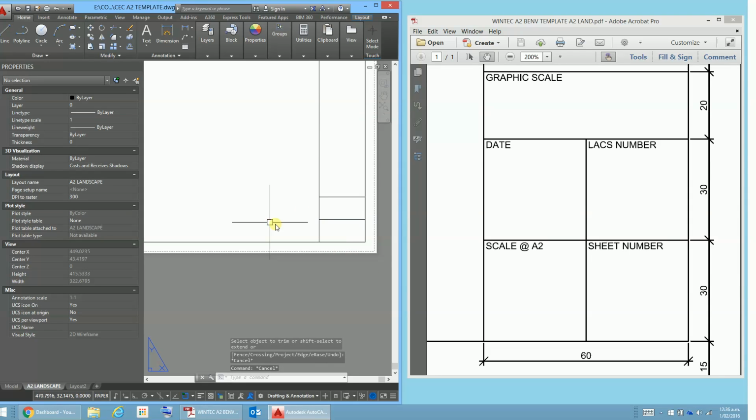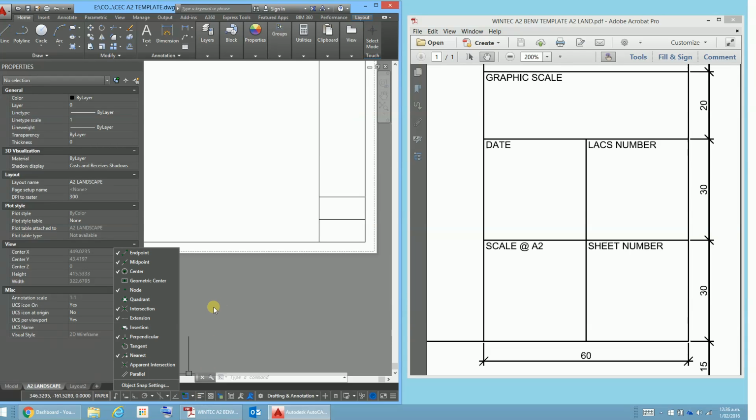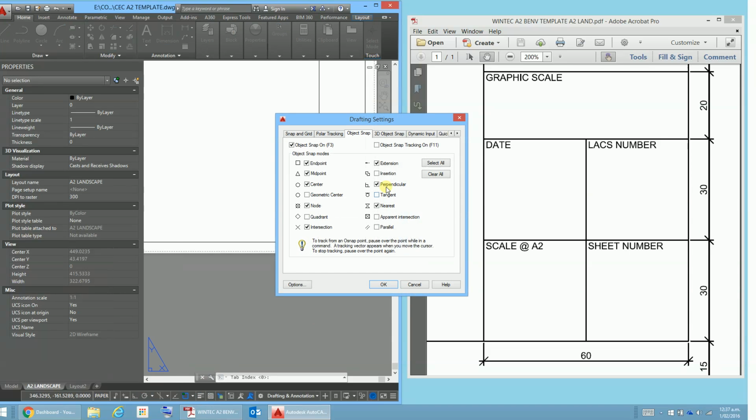Now here's an interesting little thing. We want to get this line in the middle here, and we have this little square here, the snap cursor 2D reference points. You can see that little blue square with a little star in the corner, and if we click on there, it gives us a whole lot of different settings. What these are, are the snaps. So when the snaps are turned on, the object snap settings, we can go, well, that's then there: the end point, midpoint, center.